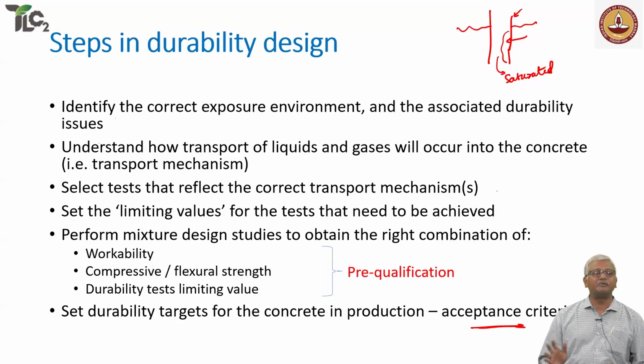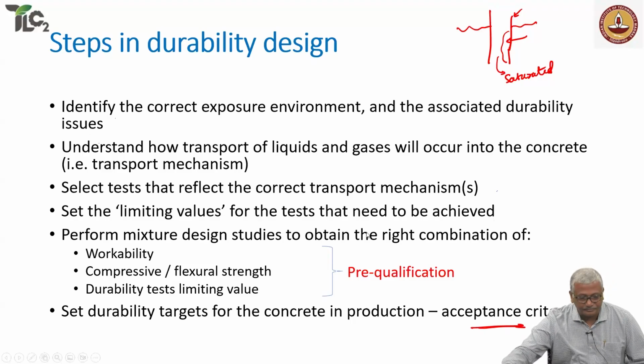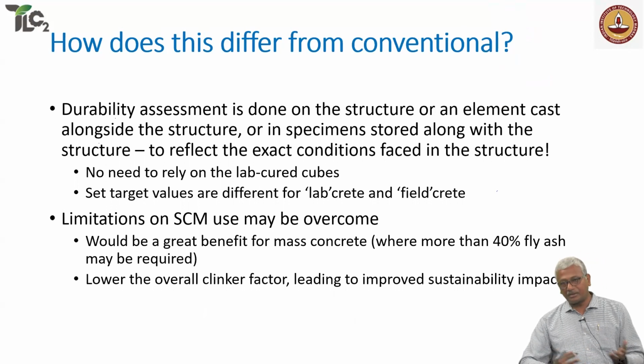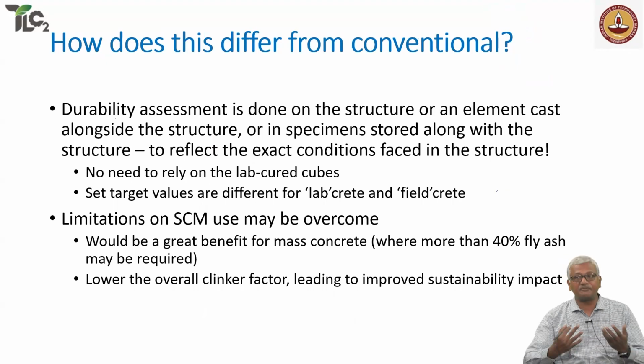Okay? We are comfortable with strength-based design, no problem. People can handle it. But when you have to pre-plan, when the producer and the contractor and the owner need to agree on a strategy for controlling durability, all of that needs a lot of pre-planning, a lot of education, a lot of understanding on the parts of all the parties involved. So conventionally, of course, as I said, we are looking at laboratory cured specimens, but in specifying a performance approach, you can also start looking at field based specimens.